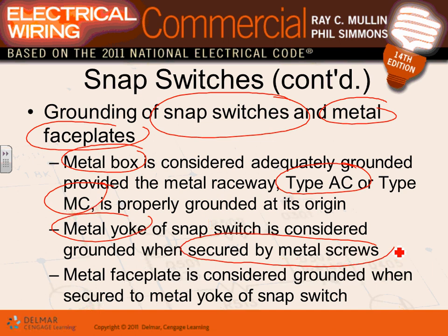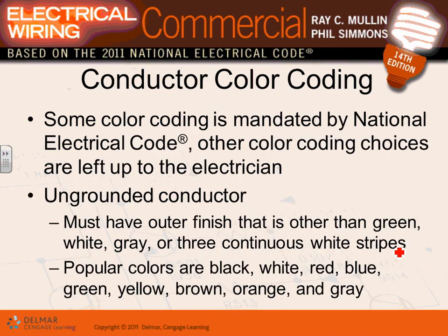So long story short, receptacles and switches must be grounded: the device itself, the cover, as well as the box. If they're non-metallic, you pigtail them. If they're metallic boxes, you depend on the metal-to-metal contact of the switches and the plates to be grounded.